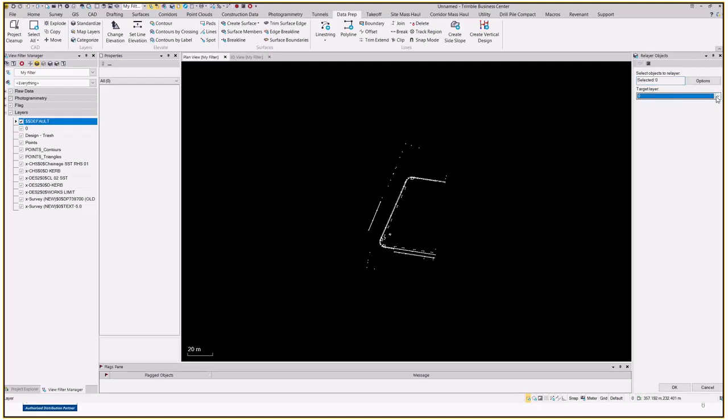And at the same time, if you set this as a shortcut command, you can quickly go through and select something and shortcut it. Control L, for instance, is what I've set, and I can quickly relayer everything that's in my selection without having to go through a whole bunch of button clicks. So as an example, I'm just going to select some of this information here.